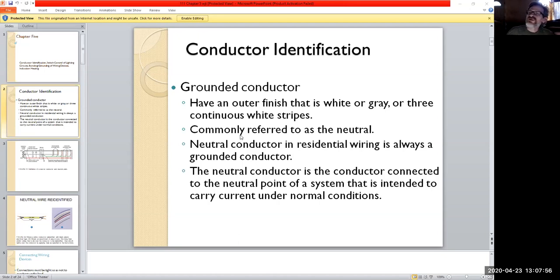So receptacles always got a 1.5 loop tape wrap around the terminals. Switches, same deal, 1.5 loop turn. You want to basically keep the bonding screws on those devices covered, so that if you had to pull it out, it's like a safety precaution, if you will. Good rule of thumb, good practice is always wrap.